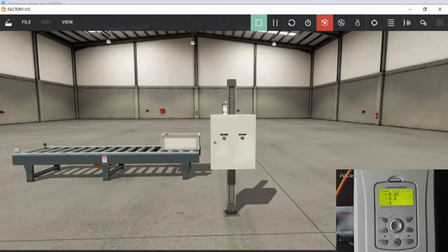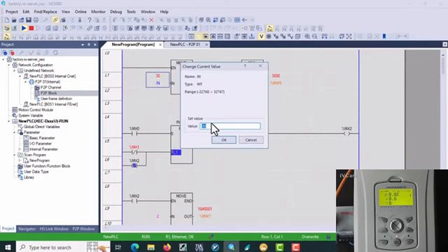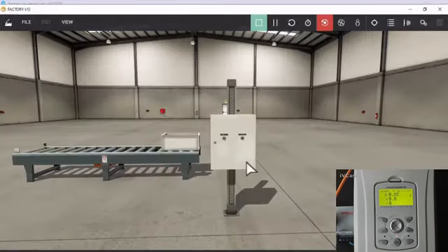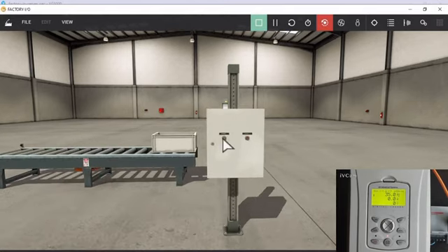For example, let's say I set a value, a frequency of 50 Hertz, or maybe not. I'll set the inverter to 35 Hertz. You can see that the number 35 appeared on the inverter's monitor, meaning my frequency is now set to 35. Alright, you can see that the monitor displays 35. Now, if I press this start button, the inverter should start running in the forward direction and my conveyor should begin to move.